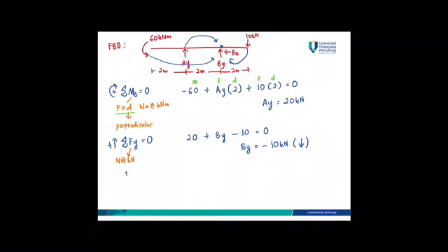And then another equilibrium equation is summation Fx is equal to 0. To the right is positive. Then Bx is equal to 0 because there is no applied force in X axis. You already get the support reaction value, and then we proceed with internal resultant loadings.